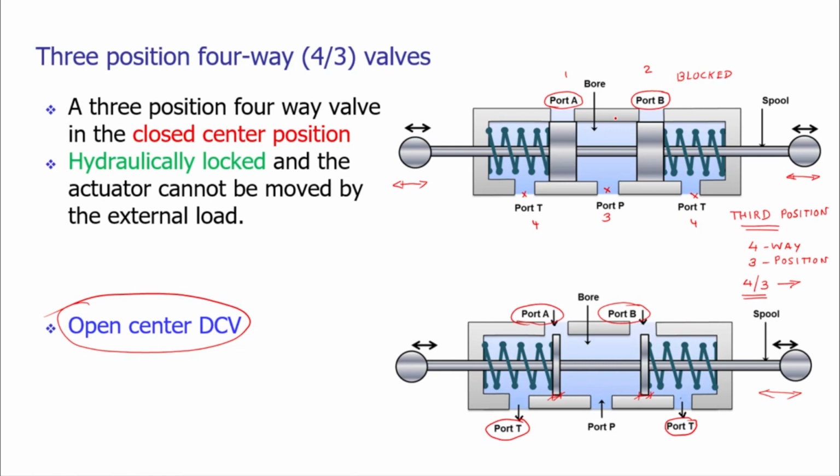Due to the continuous flow inside the system, the temperature of the system is getting increased. There is no utilization of the pressurized fluid, and the energy put into the system will be converted into thermal energy. The temperature may increase and that may lead to the failure of the system.